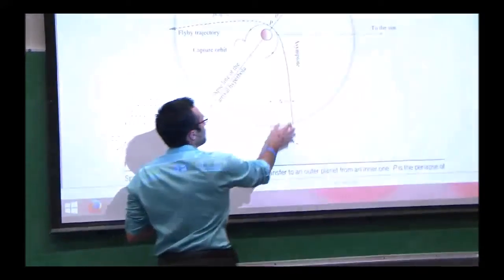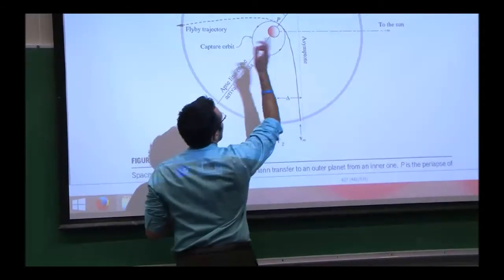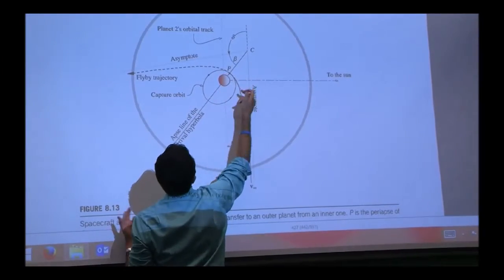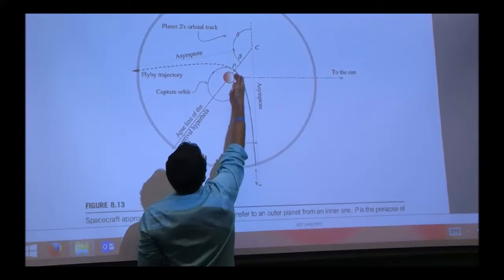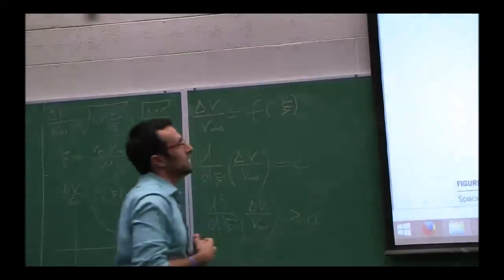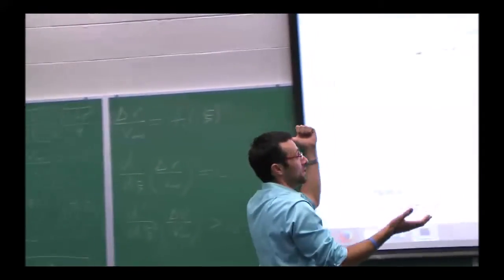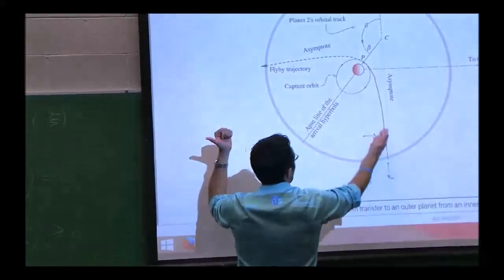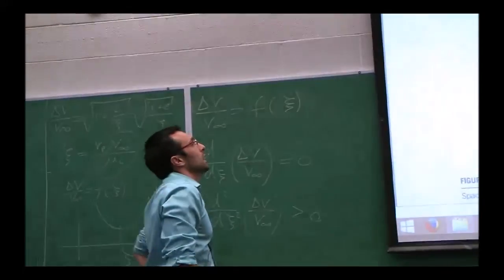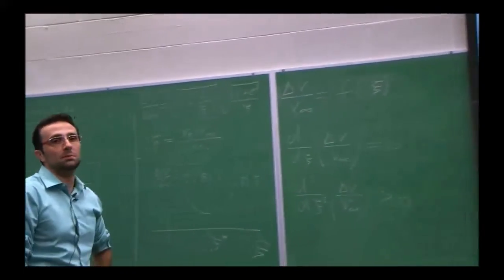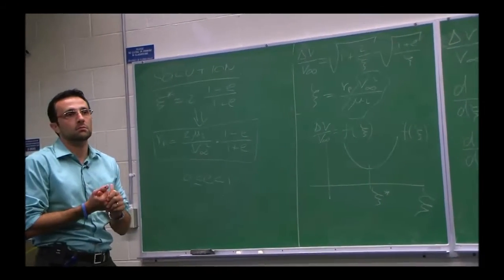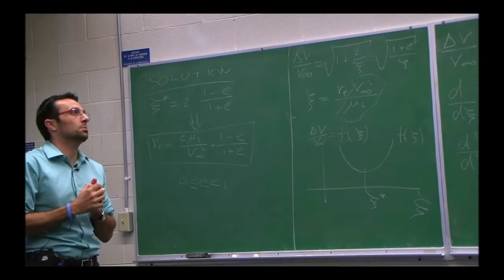So you do have control on this. Controlling this allows you to be at the right position at the perigee of the hyperbolic path, which could be the radius of the planet, so you're just impacting the planet, or it's a right RP so that you obtain a certain delta if you're doing a flyby. And so the output velocity is what you want. Again, the magnitude of the V infinity will be set, it's whatever you're coming in with, but the other side you can control, the little delta angle. And the last one is this one. You can enter into an orbit by slowing down that hyperbolic motion and obtaining a standard closed orbit around the planet.